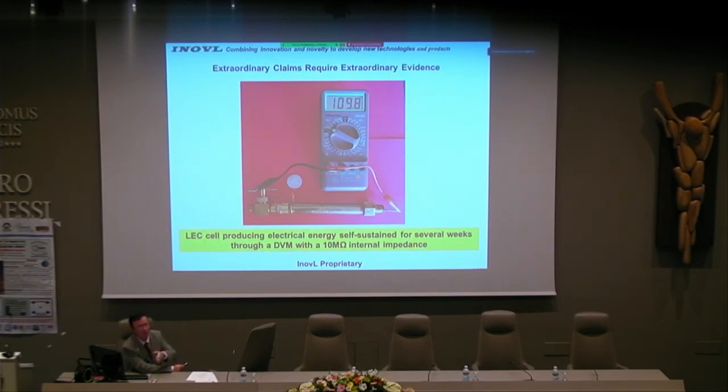You remember in the past we used what we call an electronic voltmeter, really with an electrometer tube. But with this type of voltmeter, there is a leak and an impedance, and a lot of voltmeters have 10 megaohm internal impedance. So if we record a voltage, there is also a current.